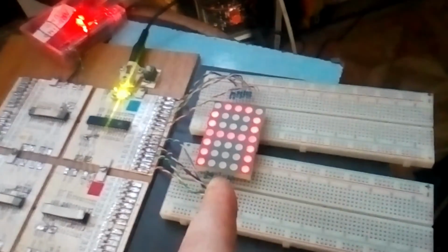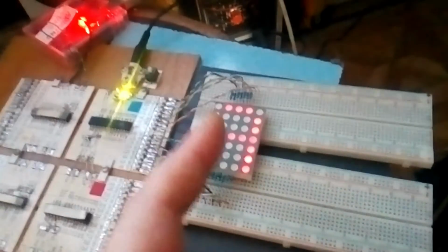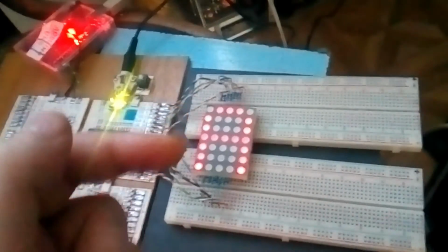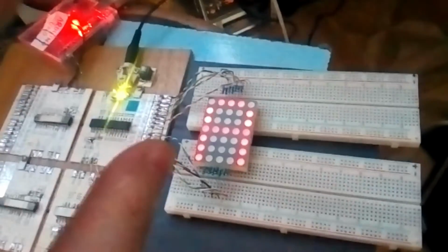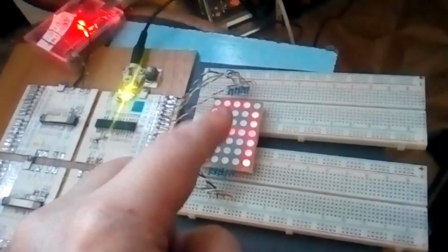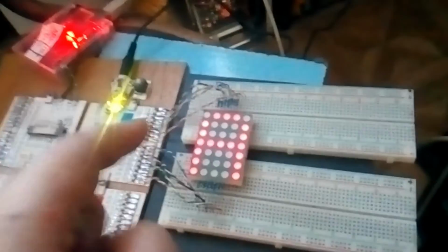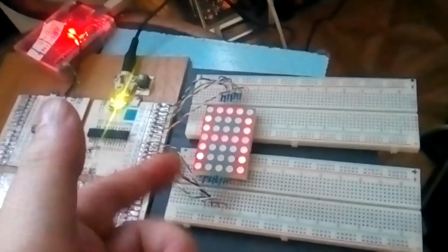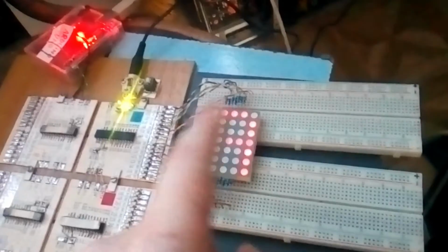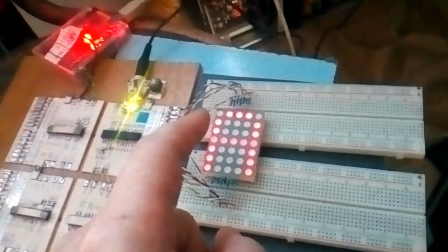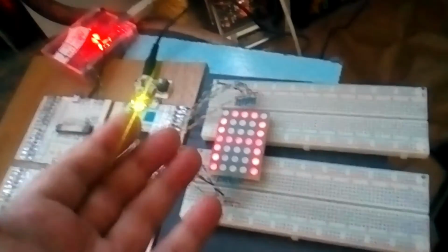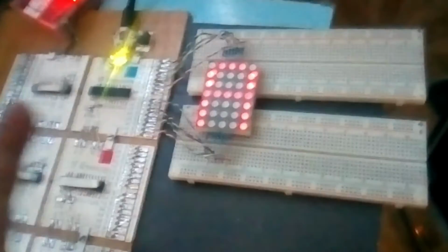Right now they are 300 ohm resistors. I switched them from 1 kilo because when I increased the speed, the LEDs got extremely dim. If I was putting daylight on top of this component matrix, you couldn't see the LEDs on, only in shadow. And right now it is not very brightly lit as well, but it is a bit more brightly lit than it was with 1 kilo per each resistor. So by decreasing the value of the resistor to 300 ohms for each of them, it got a little bit brighter, and it's a little bit better.